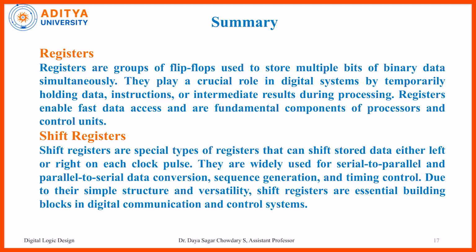Coming to the shift registers, they are one type of register, special types of registers that can shift stored data either left or right on each clock pulse. They are widely used for serial to parallel and parallel to serial data conversion, sequence generation and timing control. Due to their simple structure and versatility, shift registers are essential building blocks in digital communication and control systems.